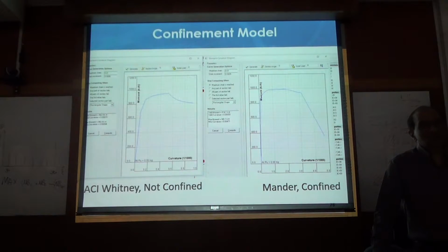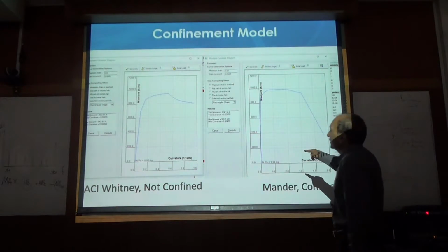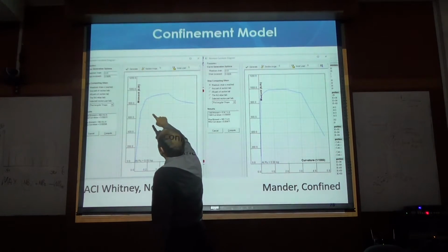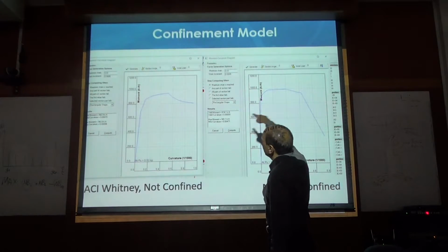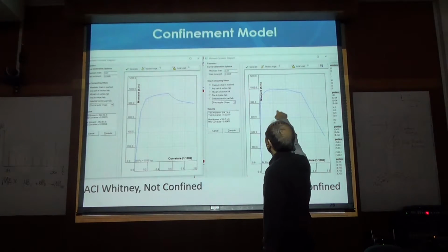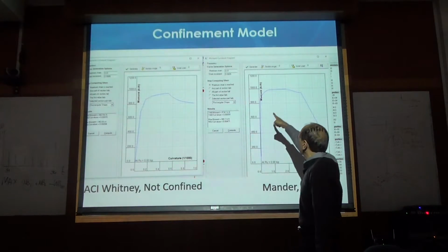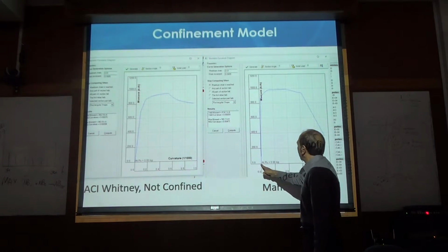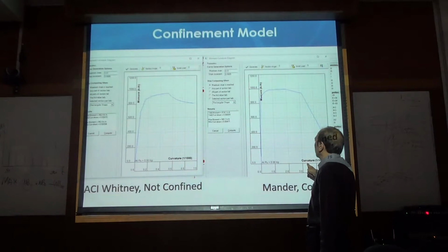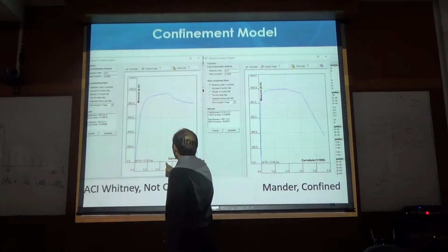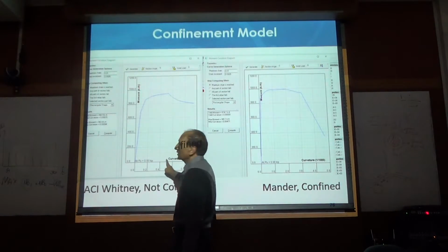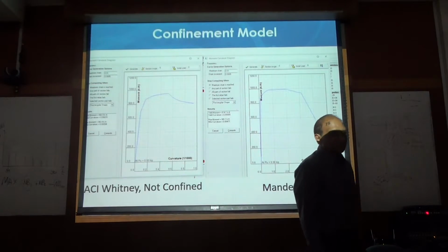Five times you could increase the ductility by using some confinement here and using the right model, right? Of course, you need a program which can do all of that, but you can clearly see that the moment capacity did not change significantly. It changed a little bit, from about 900 to about 1000 or something, but the point is that it had a ductility up to about 3.5. Here it finished at around, in fact, 0.5, not even 0.6, 0.5, so about 6 times, right?